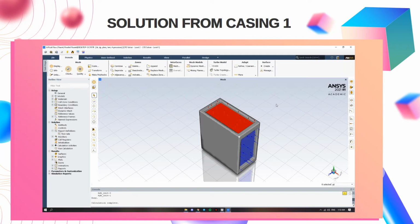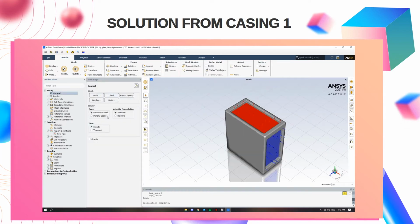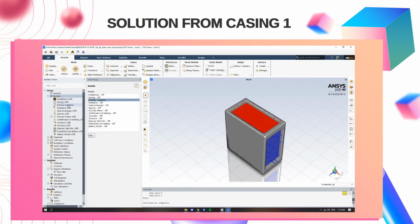This is the setup function from ANSYS, and as you can see, this is our design of the computer case. This is the design with two outlets. So let's go to the general. At first, the type we use is pressure-based, velocity absolute, and time steady. Next, the model: we use viscous laminar because this is the steady airflow.